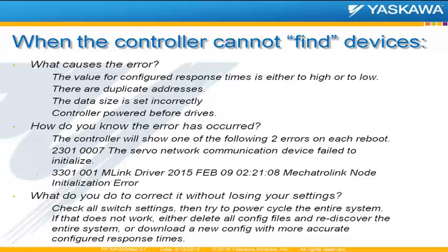If you're really not sure what to set the response time, you can always open a new project, power cycle the whole system, and just let the controller find the devices, go online from your new project, and you can record what measured response times the controller sees.